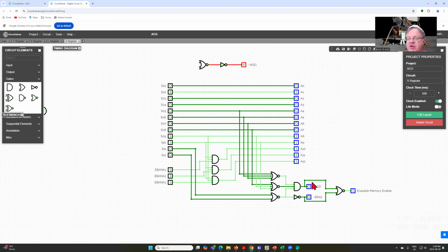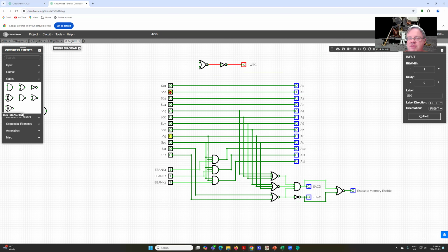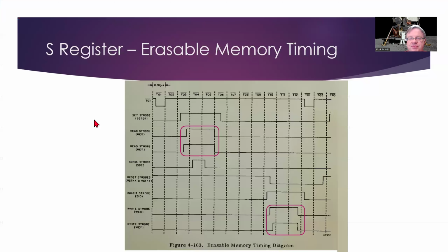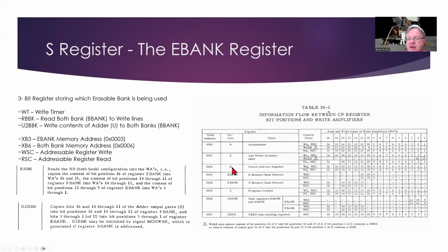And this down here is the logic that we had talked about. If we have a scenario where all of these are 0, in this case we just got bit 1, so we're actually addressing memory address 2. We will say, disable access to erasable memory, because in this case, we actually want to be reading and writing data to the, number 2, I believe, is the Q register. Let's just pull it up. Yes, the Q register.